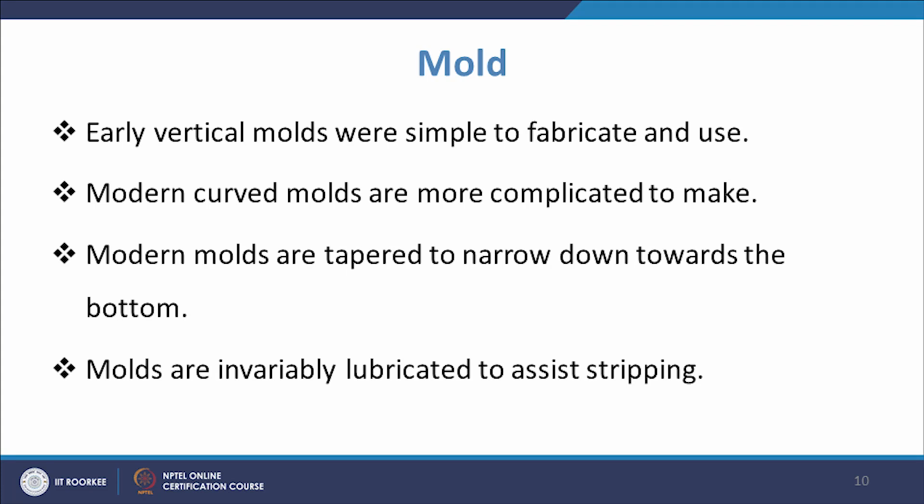The mold is also invariably lubricated to assist the stripping. As we have discussed, there will be some lubricating mechanism between the mold wall and the liquid metal which gets solidified in the skin, so that there is no sticking and there is proper stripping of the product from the mold. That also is ensured by choosing proper mold lubricants.